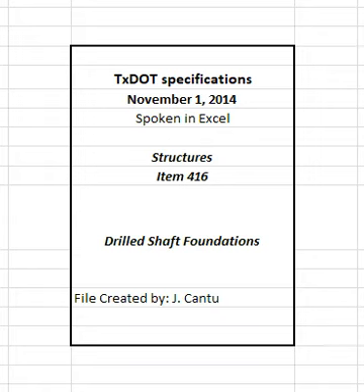Premix slurry in a reservoir with enough capacity to fill the excavation and for recovery of the slurry during concrete placement. Do not mix slurry in the shaft excavation or other hole. Allow adequate time for hydration of the slurry before introduction into the excavation. Maintain a head of slurry in the shaft excavation at or near ground level or higher, as necessary, to counteract groundwater pressure during and after drilling.